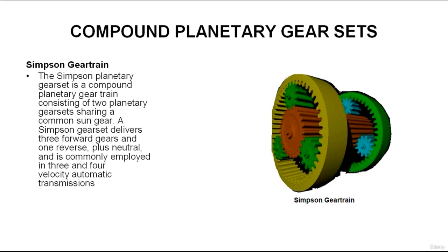For the most part, each automobile manufacturer uses different parts of the planetary assemblies as inputs, outputs, and reaction members. The role of the planetary members also varies with different transmission models from the same manufacturer. There are also many different apply devices used in the various transmission designs. A Simpson gear set can provide the following gear ranges: neutral, first reduction gear, second reduction gear, direct drive, and reverse.